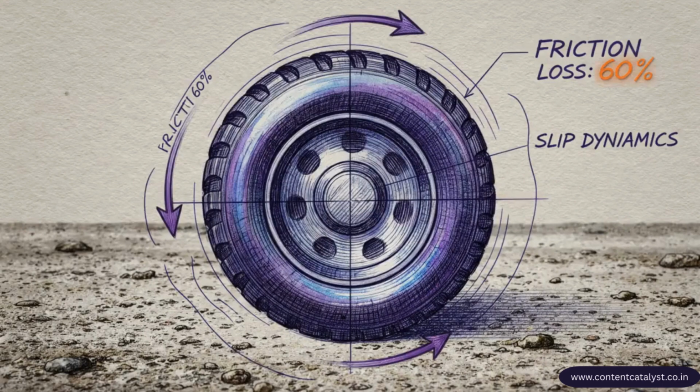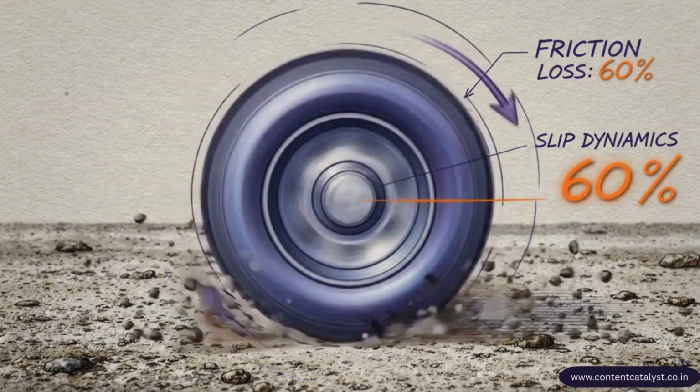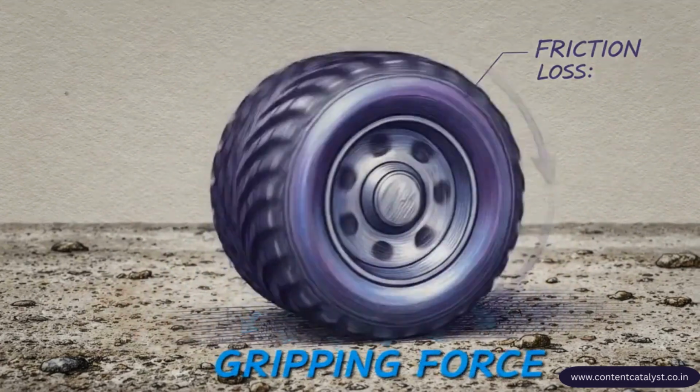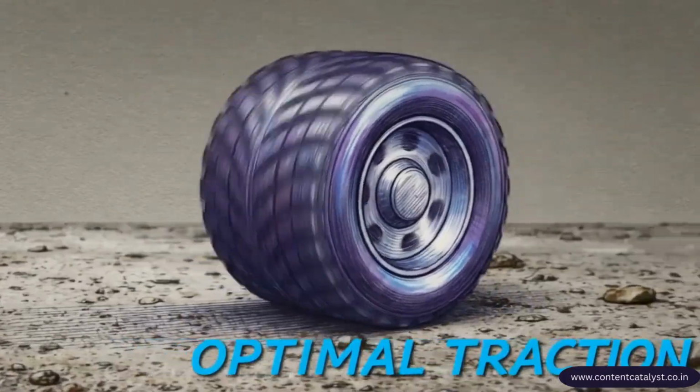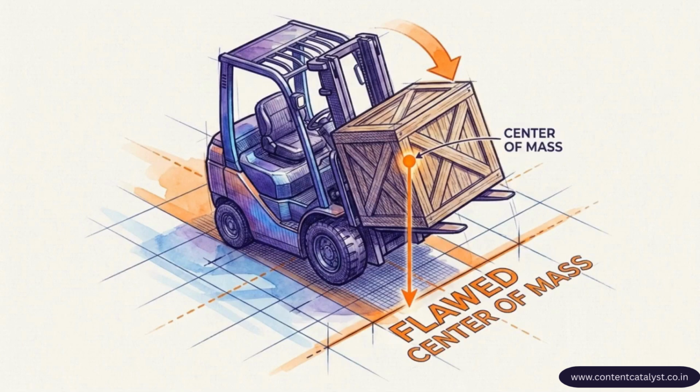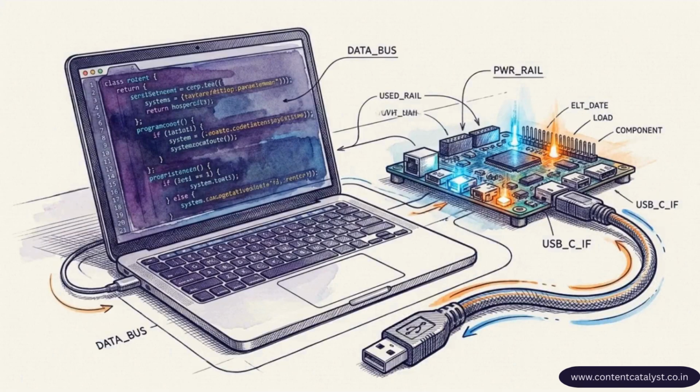That iteration cycle must account for reality. A slight wheel slip on a dusty warehouse floor causes a purely kinematic simulator to fail immediately. Webots handles these edge cases by modeling rigid body dynamics. You can identify physical design flaws, like a top-heavy center of mass tipping a payload, before you ever build the prototype.